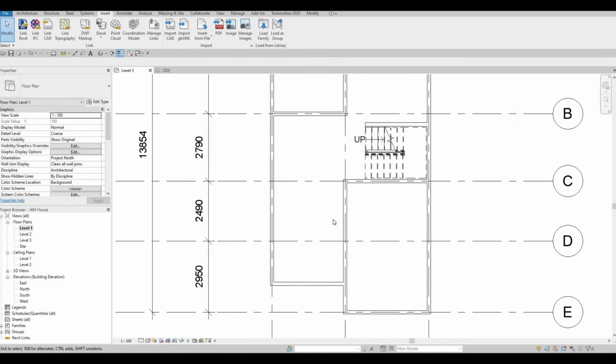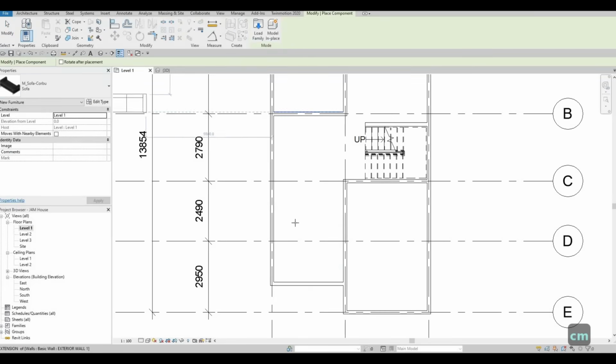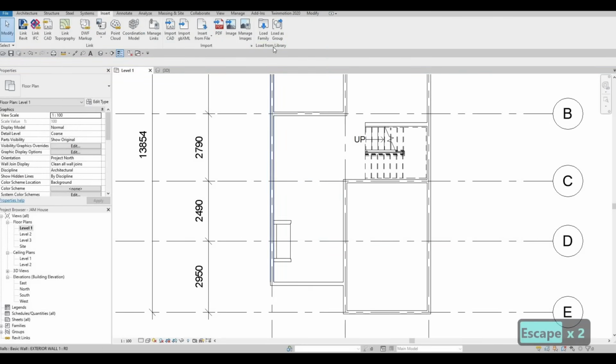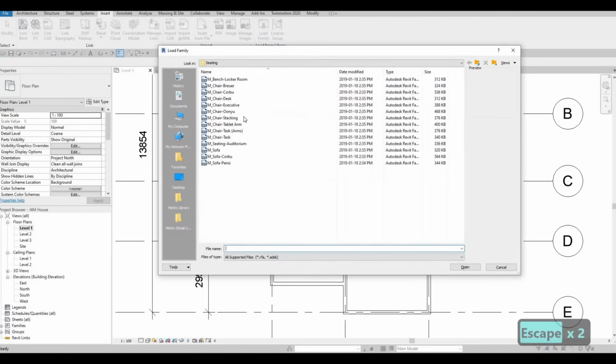and then what you need to do is you need to load them one by one. So I loaded that one, and then now I could type in CM, so that is component, and then you'll be able to add it instantly. So you can press spacebar to change orientation. So I'm gonna add it right there, and then we can add in some chairs. So that's the trick. Load them one at a time, and then you'll be able to use CM so that you don't need to look for it.